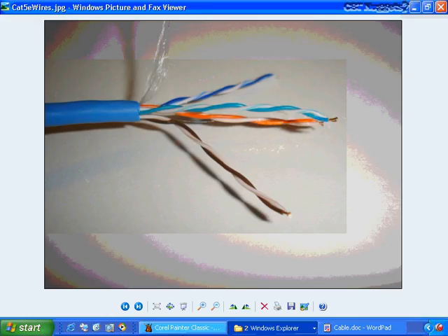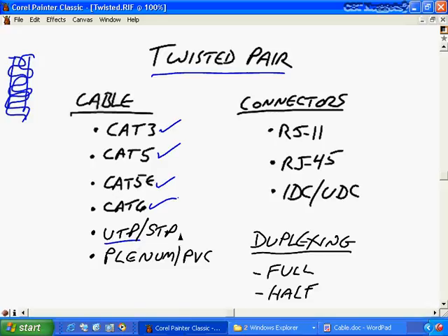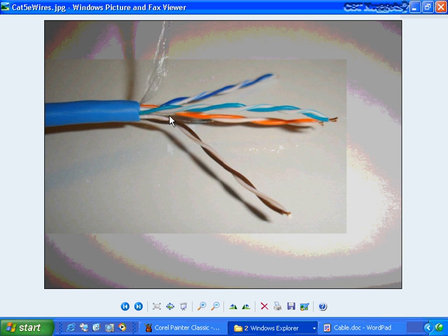The shielded twisted pair, or STP, type of cable is going to be quite a lot different, actually. It's kind of like taking that unshielded twisted pair and putting it inside of a coax cable, because around each pair of wires, like around this pair of wires, you'll have an insulator, and then you'll also have shielding around these as well, something like the foil you might see in coax cable, and that foil goes around all the twisted pairs. Then outside of that shielding, you'll have a shielding braid, and after that, you'll have the external jacket that we see here.